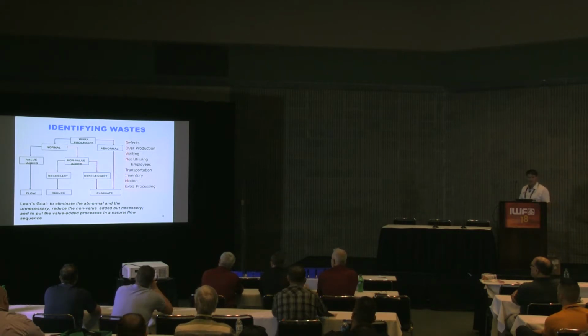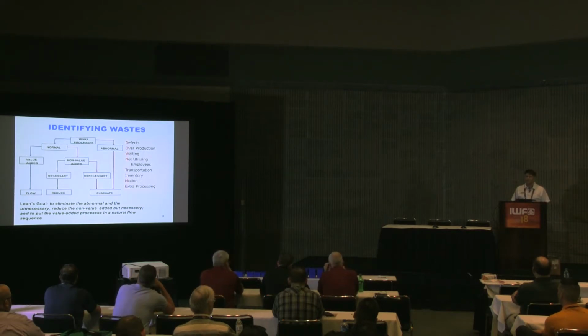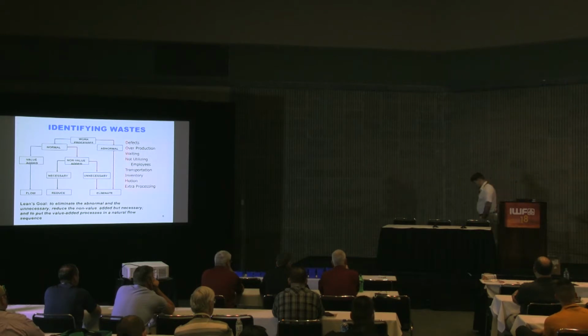Extra this, extra that. I always get comments, oh, well, it's only a few seconds. I say, well, it's only a few seconds times a million times. Or it's only a few steps times a million steps. Right? I did a study on an edge banding operator with a client down in Maryland. I said, why don't you have a return conveyor on this edge bander? He's like, why? That return conveyor is $80,000. I said, yeah, but it's worth every penny. So I analyzed how many miles he walks in a day. He walks about 8 to 9 miles a day within the width of the stage, just walking back and forth. I would quit if I were him. I wouldn't last a week. I'd quit. The paint's all worn out. You can see the concrete's worn out, just walking back and forth all day, right?